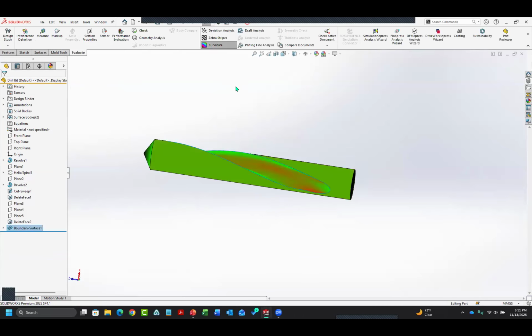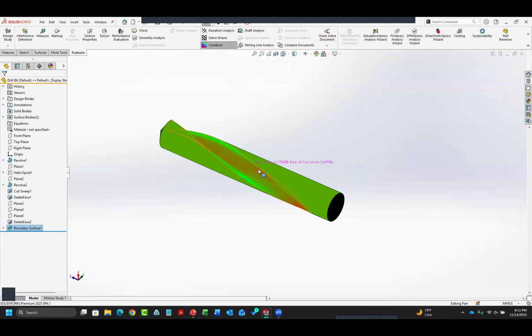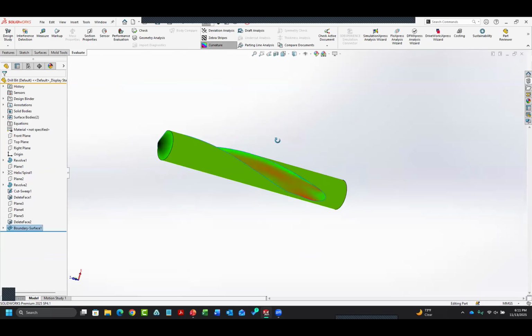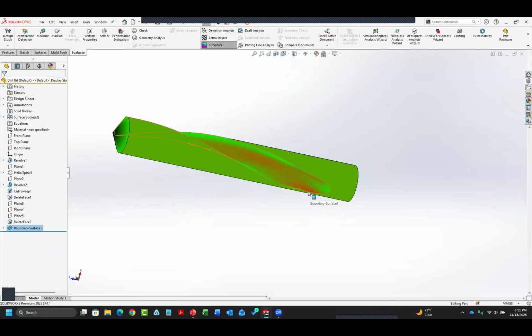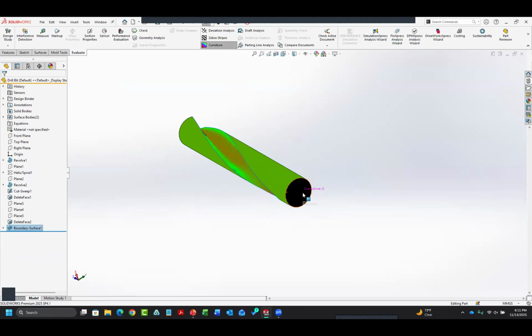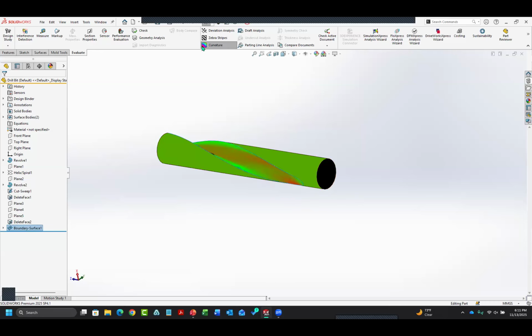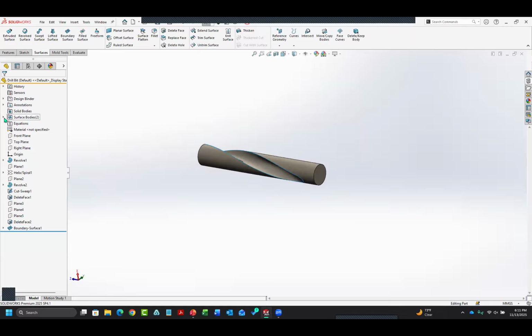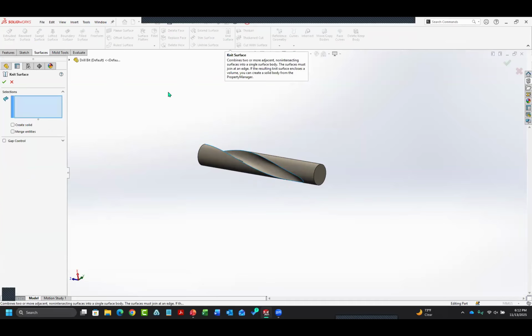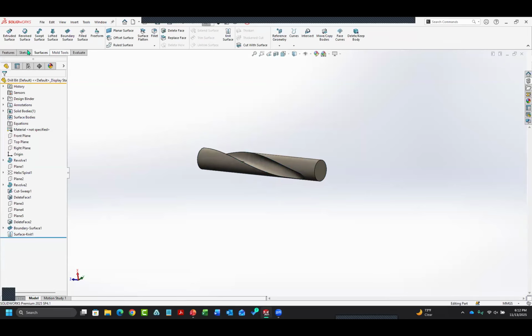So if I were to take a look at the curvature, looks pretty good. We even have kind of a little section. It's very symmetrical. And even though we do have a little bit of a curvature shift and deviation, it's not black. Black faces are 0. So that was black when we started. When we start talking about surfaces, right now I have 2 surface bodies. The end goal is normally to have a solid. So the knit surface allows me to choose 2 or more surfaces. And again, if they are volumetrically airtight, I can say create solid, goes ahead and creates a solid.